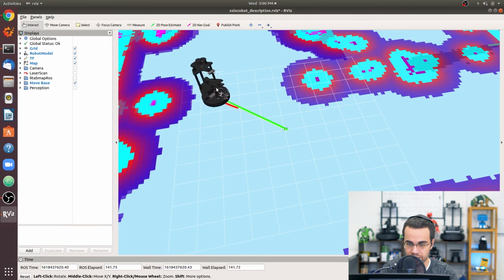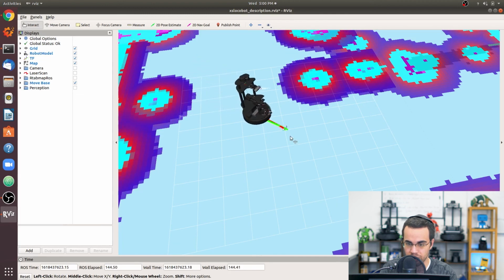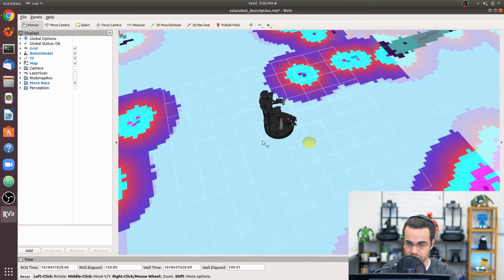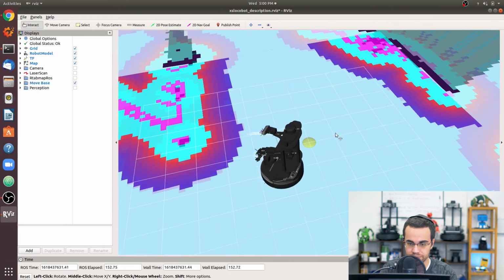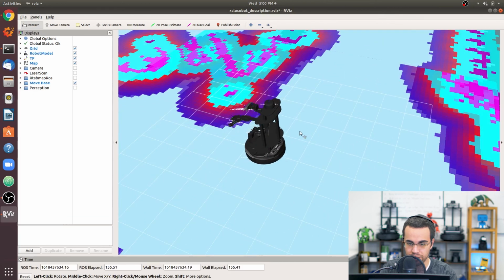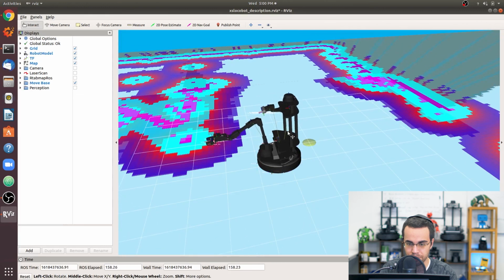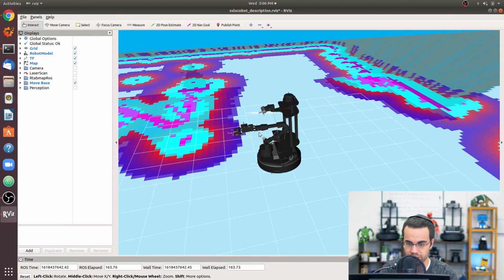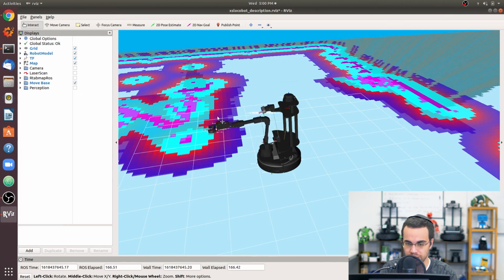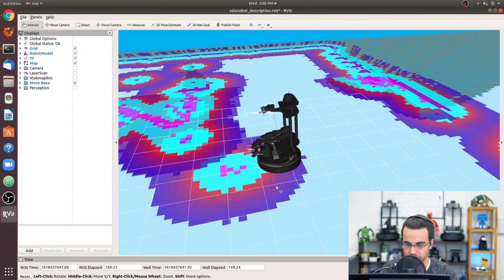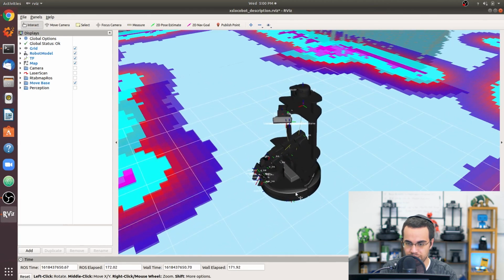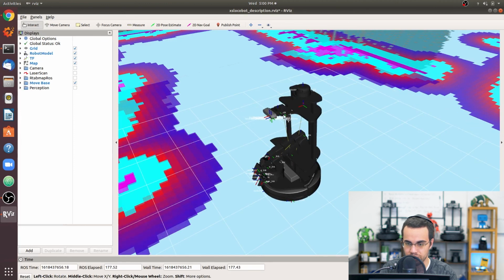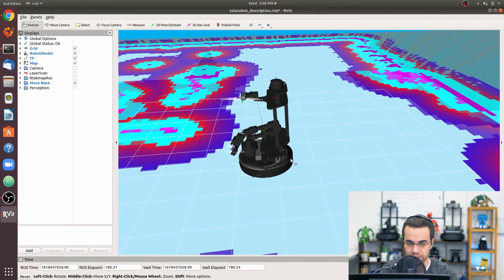And then right after it finishes that goal pose, I tell it to go back to 0, 0 with an orientation of 0 as well. So essentially back to where it started. And afterwards, I think it's called the EE Cartesian trajectory script, where it essentially draws us a square in space with the end effector of the arm. Then it pans and tilts the camera servos before bringing it back to its home positions. And that's the end of that.